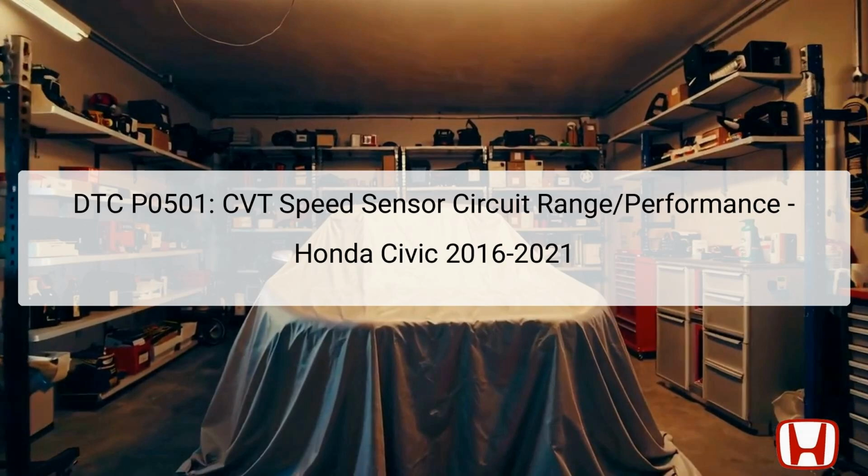The CVT speed sensor is mounted on the outside of the torque converter housing, an essential component that monitors the rotations of the secondary driven gear. It sends a pulsing signal to the transmission control module, often abbreviated as TCM, which processes this signal to manage gear changes effectively. If the sensor fails to transmit these signals, the TCM identifies this malfunction and stores the associated DTC. Understanding this diagnostic code will be vital for accurate troubleshooting and resolution of the issue.